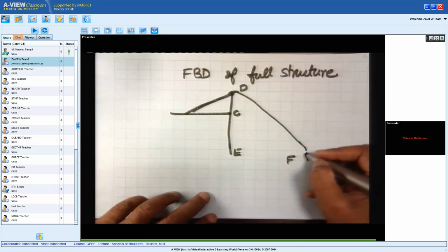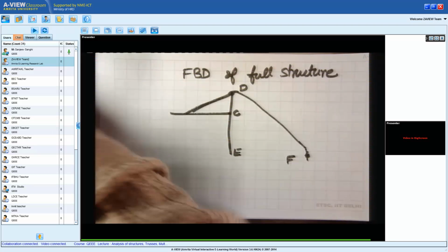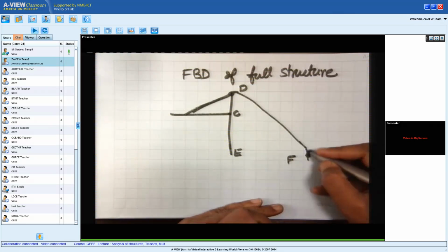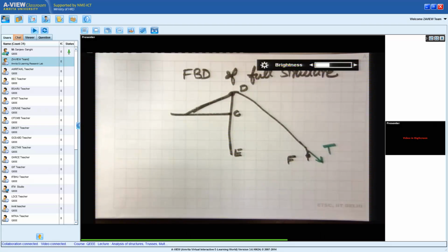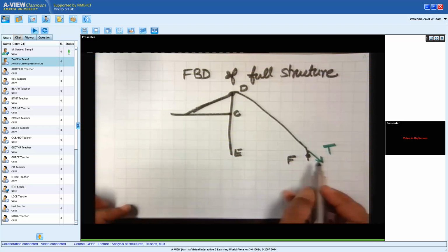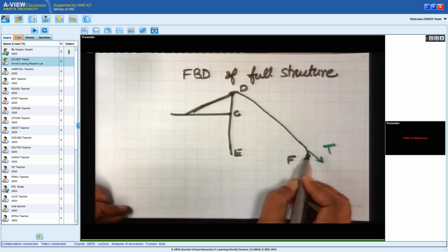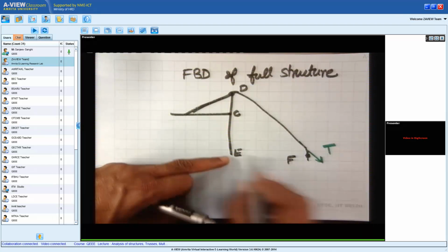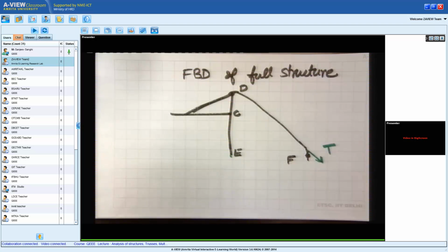So now at point F, what am I cutting? I am cutting a string. So what will come in the free body diagram as the effect of F? It will be just a single force shown by T along the direction of the string. And now it will become very clear why I was saying we cut it as close to F as possible. We cut it as close to F so that when we take moments about T, we will only get one component of the force.